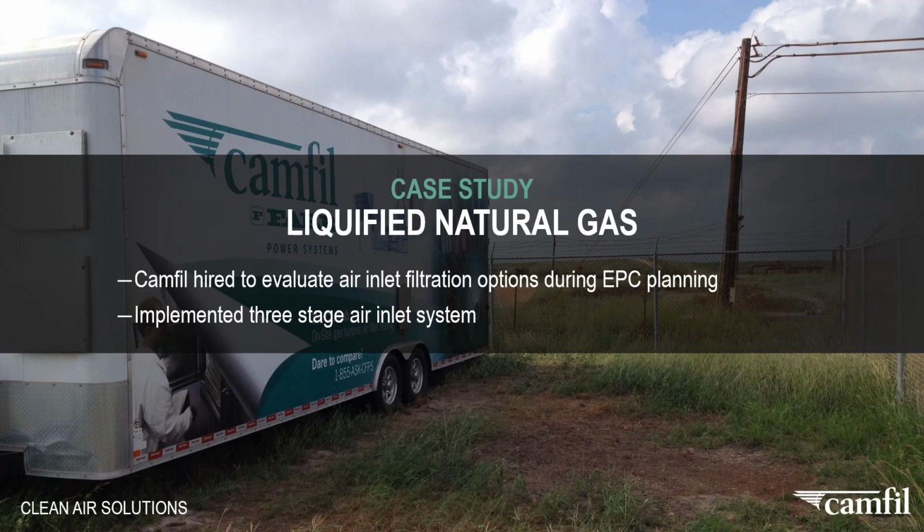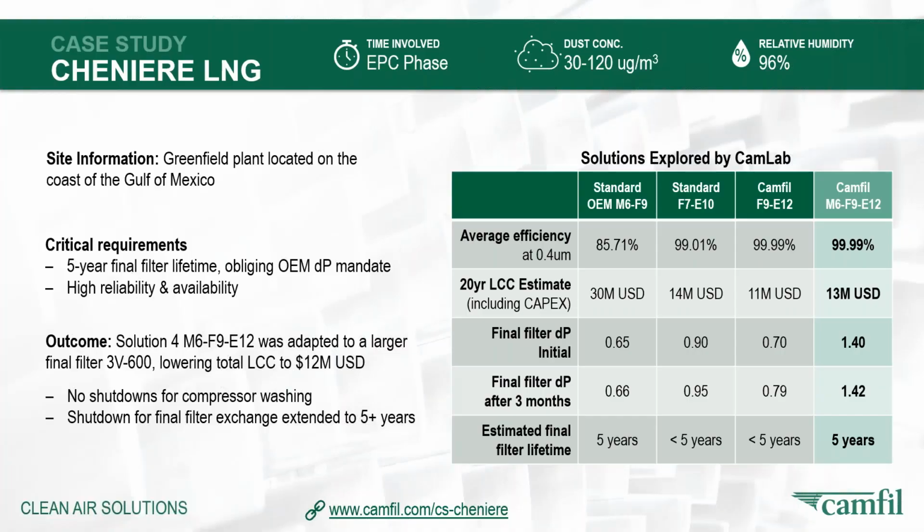As you can see in this picture, there was this CamLab trailer that we put on the greenfield site. We tested 4 different combinations of filters within that system, and we tried to simulate, based on the ventilation systems that we run in there, the same airflow through the filters that they would be running on the gas turbine, and then simulate how they would operate under the typical environmental conditions on that specific site.